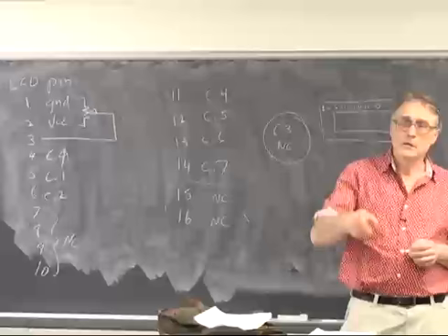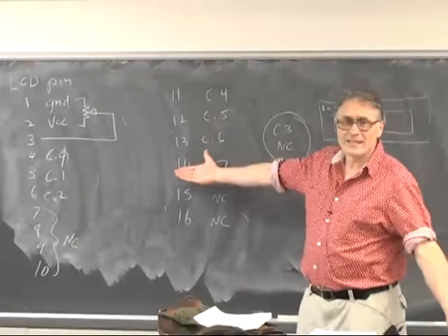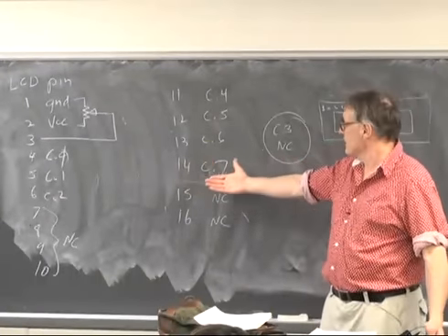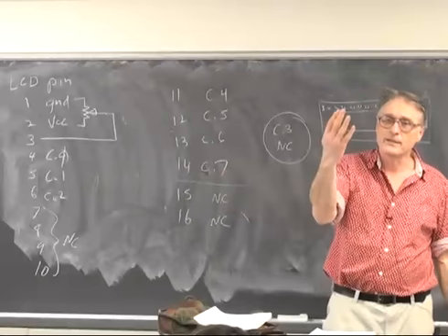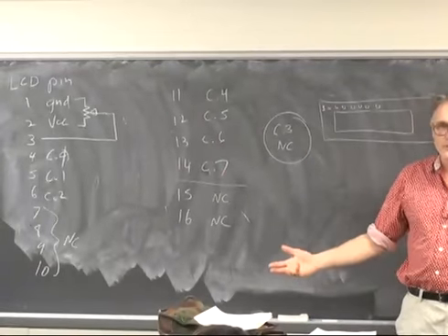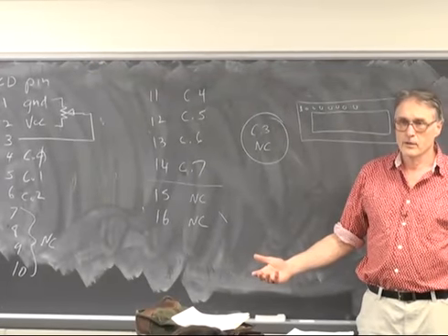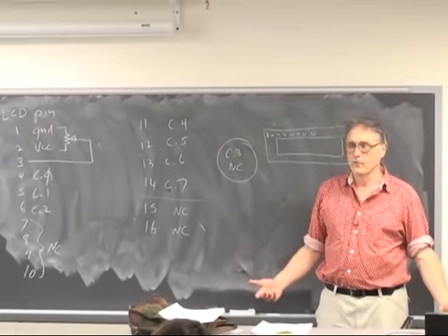There was a question. It's not used for the LCD because it's a 4-bit data bus, 3 control lines. No, port C3 is a perfectly good port. You can use it for anything you want here. You could blink an LED off of it if you wanted to.